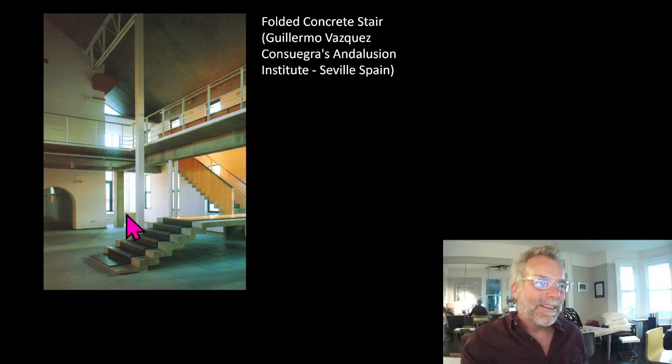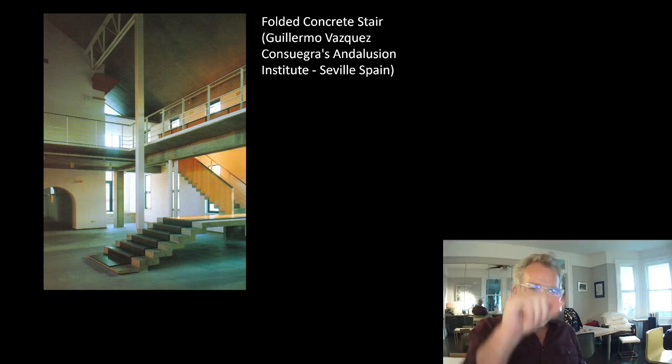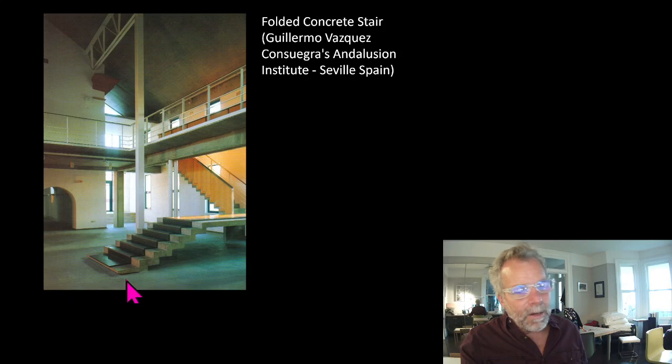Come on. So doing this in concrete is a challenge. And the reason it's a challenge is that it's not that the concrete's not strong enough. If we look at the thickness here, it's maybe 6 inches, 150 millimeters thick. We know that the depth to span ratio for concrete is around 20:1, which means we can go almost 3 meters with 150 millimeter thickness. That's not a problem. This may be pushing a little bit, but not too much.